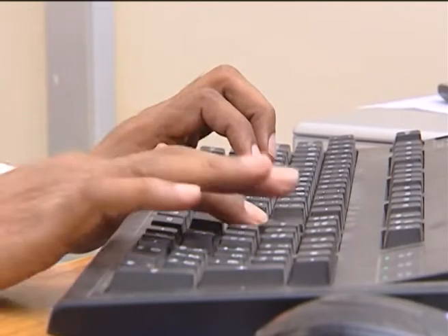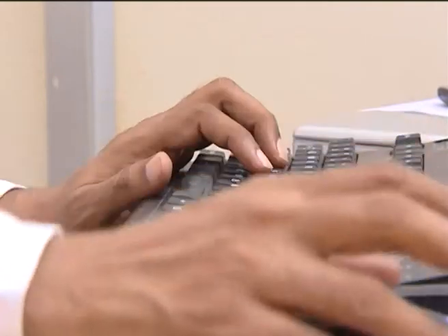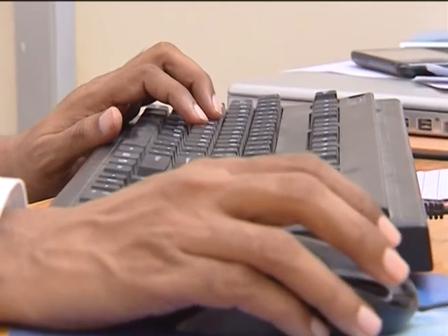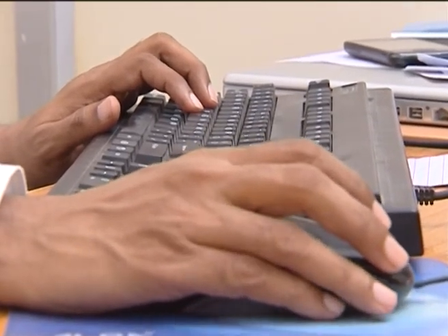For example, pressing a key on the keyboard or moving a mouse sends a hardware interrupt signal that causes the processor to transfer the control to an interrupt service routine. The ISR is a routine which reads the keystroke or the mouse position and responds accordingly. The hardware interrupts are asynchronous and can occur in the middle of the instruction execution. However, the processor finishes the current instruction under execution and responds to the interrupt before the execution of the next instruction. So, this is about hardware interrupts.